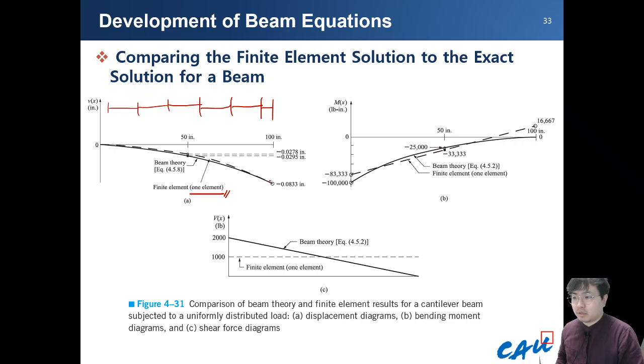The displacement shows a very small error compared to the other values. It is because, although we use a very simple, lowest order displacement variable, this is basic Euler beam theory, actually the same, so there is no big difference between the beam theory and the actual FEM solution. However, due to some numerical issues, they can generate some difference.